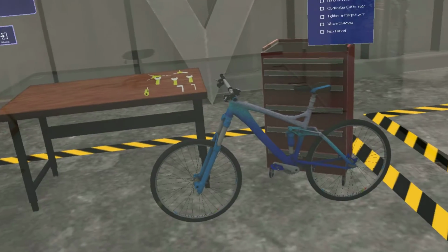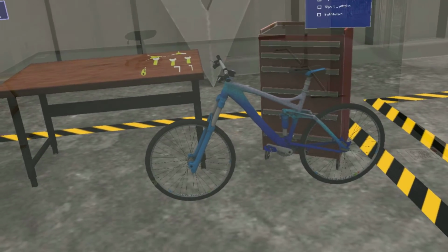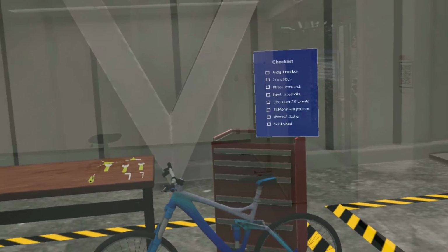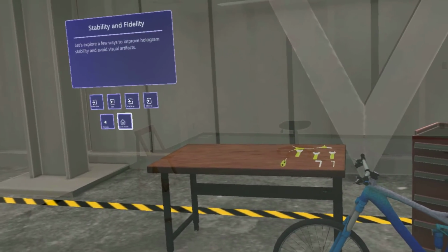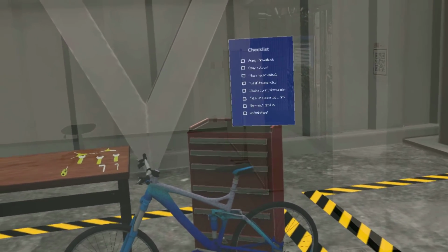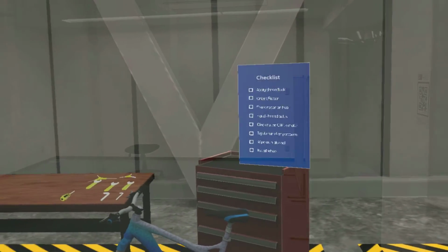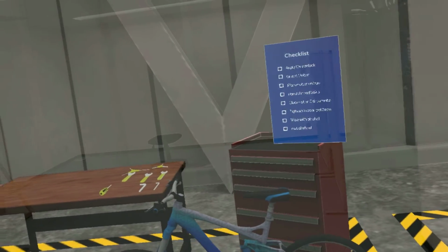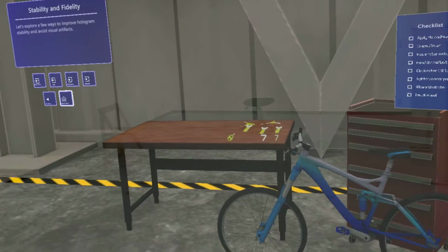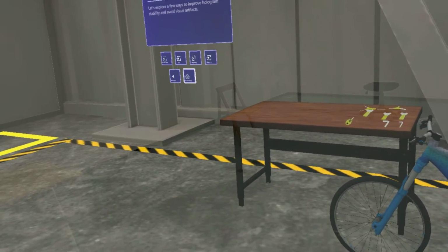Did you notice that the text on the task checklist panel sometimes shimmers or looks jagged and is hard to read? Also notice the shimmer on the wheel spokes. This is called aliasing. Unity's Text Mesh Pro and MRTK shaders substantially reduce text aliasing. For 3D assets, avoid using thin and high contrast geometry if possible. Compare the difference for yourself.